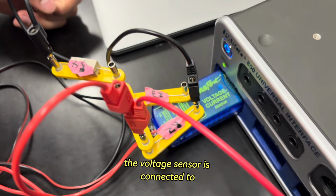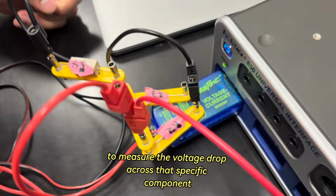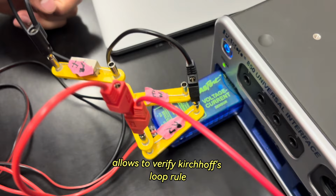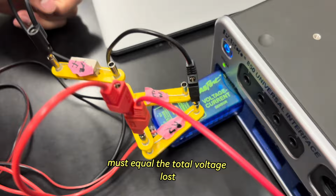The voltage sensor is connected in parallel across a resistor to measure the voltage drop across that specific component. Measuring the voltage difference across the resistors allows us to verify Kirchhoff's loop rule, which states that the total voltage gained in a loop must equal the total voltage lost.